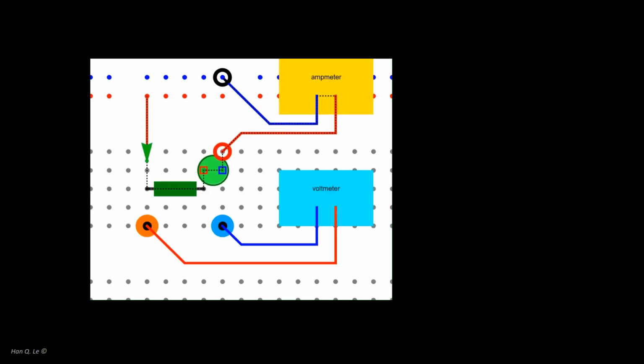If the circuit works, but the LED goes dark when doing the measurement of the current, envision whether the current flows through the ammeter with the correct ports. If the current flow path is correct, but there is no current reading, try to switch the current probe from the milliamp port to the amp port. If there is still no current flow, one high probability reason is a problem with the fuse.